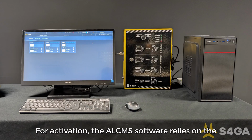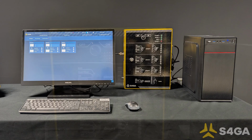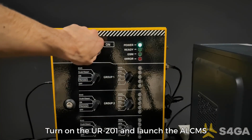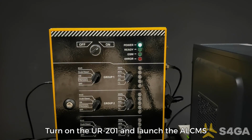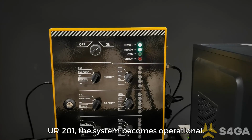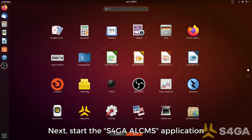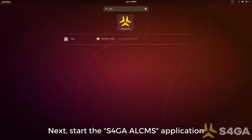For activation, the ALCMS software relies on the UR201 hardware to manage the lights. Turn on the UR201 and launch the ALCMS on the computer. When the ready LED indicator illuminates on the UR201, the system becomes operational. Next, start the S4GA ALCMS application on the computer.